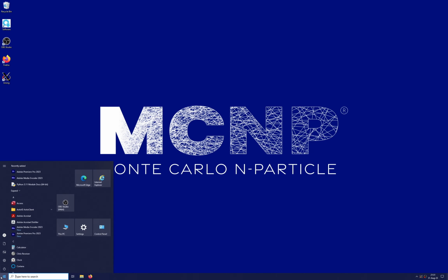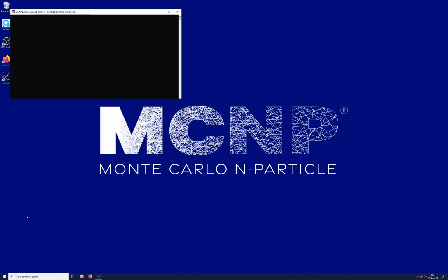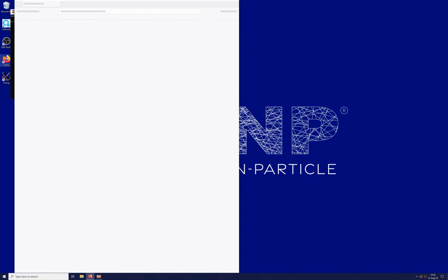To launch MCNP 6.3, we can go to our Start menu and find MCNP 630 and request the MCNP 630 command window. To test the code, we can use an MCNP input file available on the MCNP website. In this case, we're going to download the Godiva critical assembly from mcnp.lanl.gov/include/g1.txt, and we'll have a small file appear.